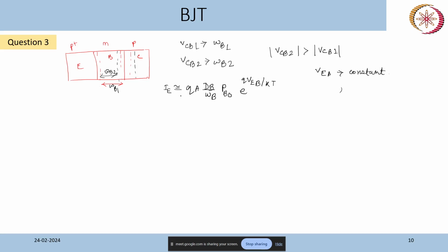So we are only considering the hole current part. The holes are traveling from the emitter side to the base side. Because of the doping concentration, as we discussed earlier, the hole current component will be significant compared to the electron current component for a PNP transistor.